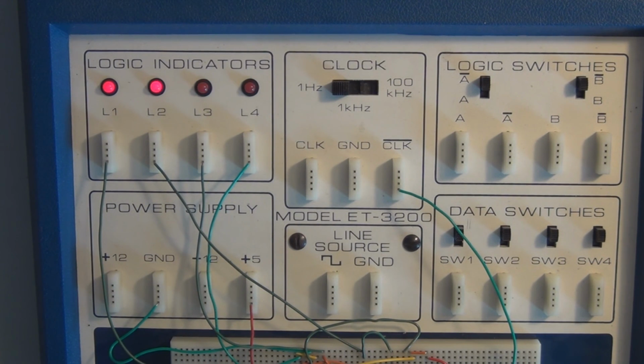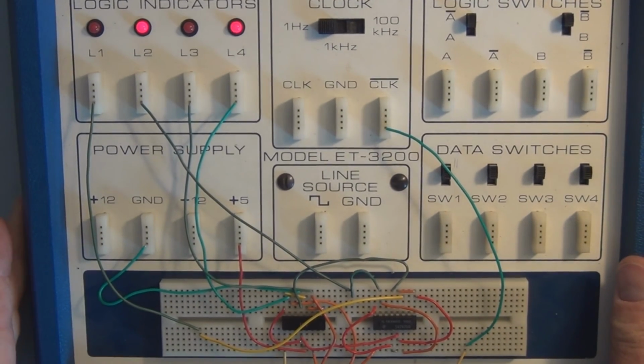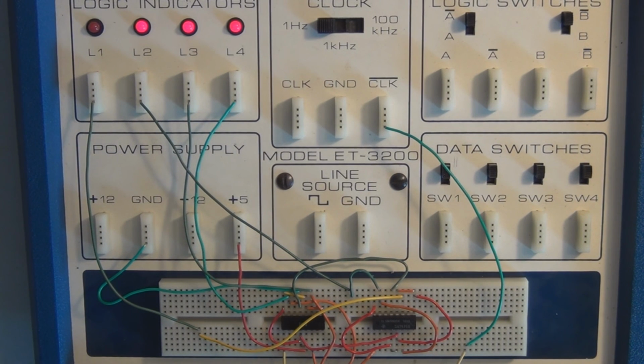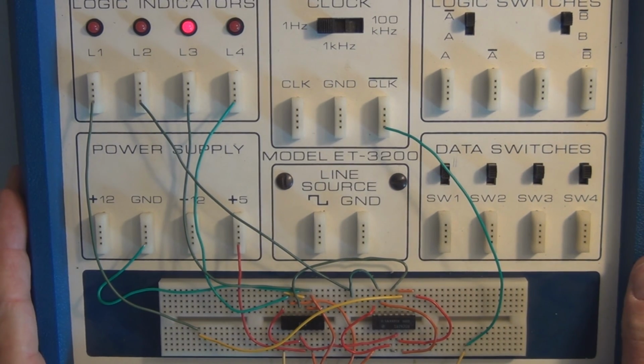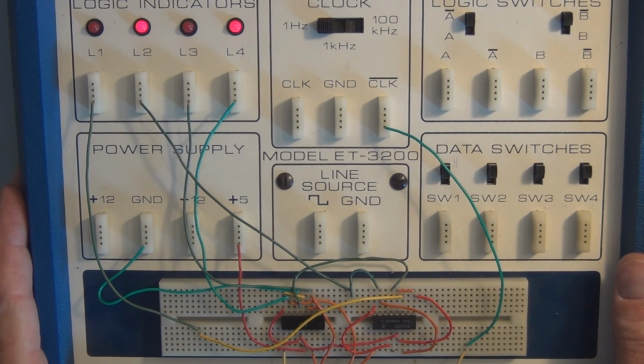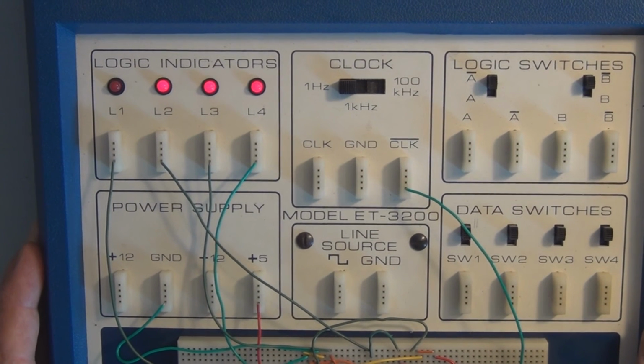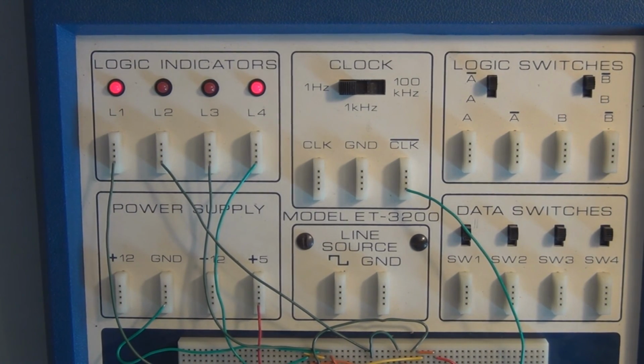So the JK flip-flop can do everything that the Set-Clear type of flip-flop can do, except it has the additional toggle feature, and one of the uses of JK flip-flops is in counting, where we feed the output of one flip-flop to the clock of the next flip-flop and proceed like that down the line, we can end up counting or also dividing a frequency. You can consider it as dividing also in addition to counting.